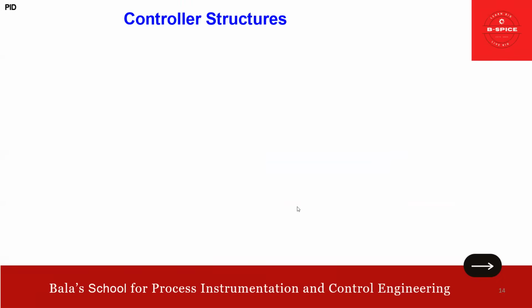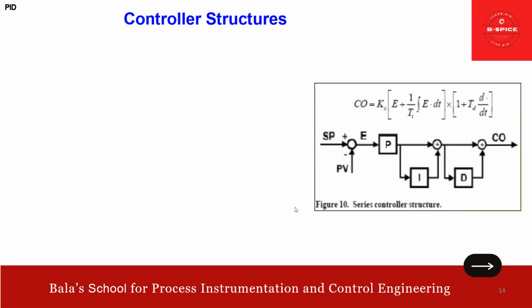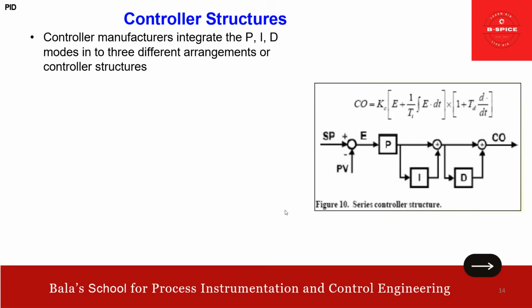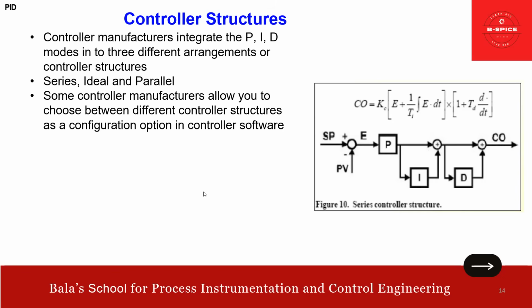Now, the second part: the look and feel, the controller structure. Controller manufacturers integrate the PID modes in three different arrangements or controller structures. One is series, another is ideal, and the third is parallel. Just remember, friends, some controllers allow you to choose between the different control structures as a configuration option.